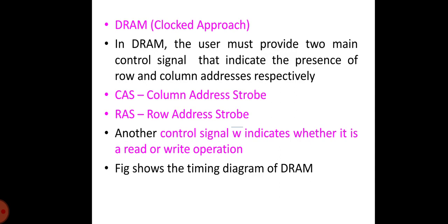Since the early days, DRAM memories have opted for a multiplexed addressing scheme where the row address and column address are presented in sequence on the same address bus to save package pins. This approach has survived many memory generations and is still in use today, although it is getting increasingly awkward and in disparity with the system level requirements.